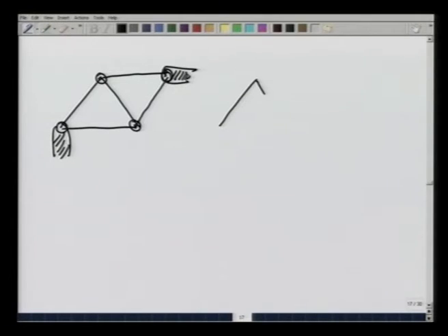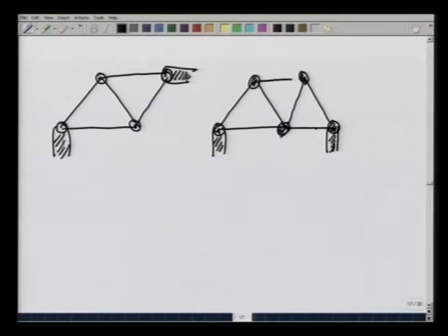Another way is I have this basic truss which is fixed here, fixed here. I do not want to fix it here now. I provide one more member, so that this point now has 3 members that can provide equilibrium to it. This is a fixed point, and suppose I want to put this under a fixed point. Then this member has one force coming from the fixed support, one from this member. So, I have to provide one more member, so that there are 3 forces acting on it. But this gives a loose end here. I could fix this loose end by putting 2 members here.